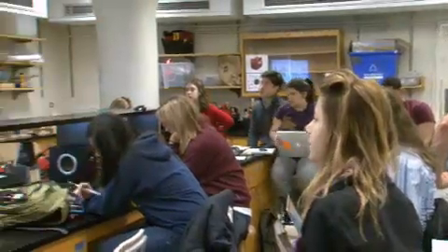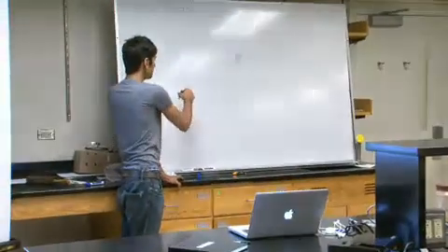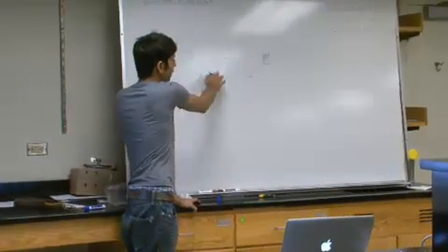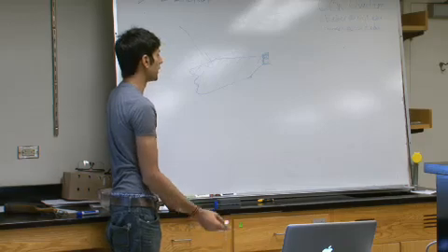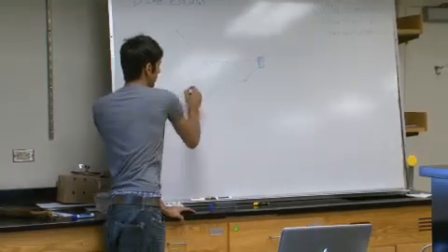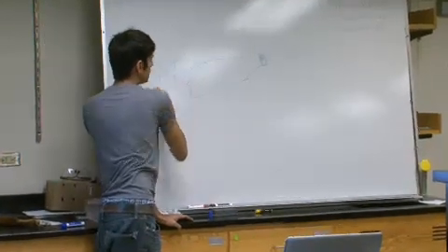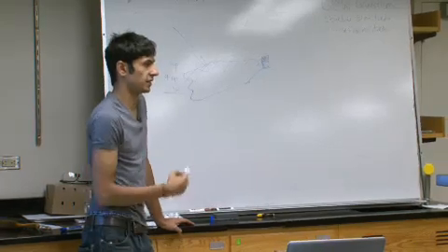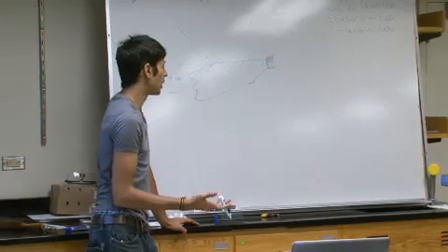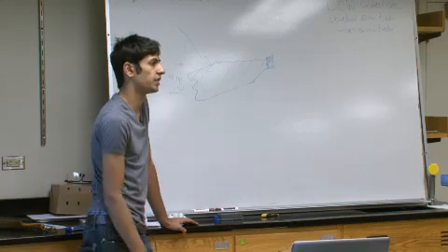Because water and your plastic both absorb some of the sunlight, you have a lot of it being absorbed by this fluid. And what they say is if this depth is more than 4 inches, SODIS's effectiveness is dropped by maybe 50%, I think is what they say.